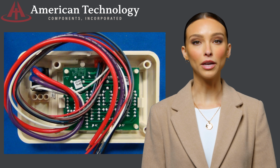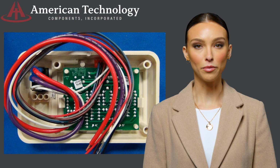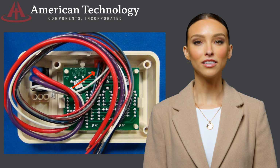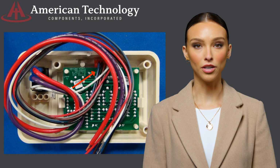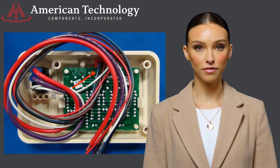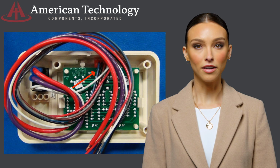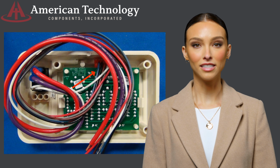The testing for the operation of the panel is also quick and simple, as in the diagnostics for the K101. We will use an M28 micro monitor as an example to demonstrate the testing of the panel circuit board. You will find a plastic red block connector on each one of our circuit boards. The number of wires will vary between 6 and 10. Pin 1 will be red and represent incoming 12-volt DC power. Pin 2 will be white and represent chassis ground.